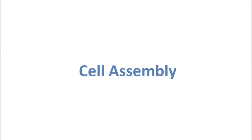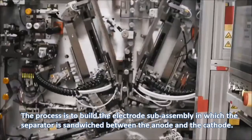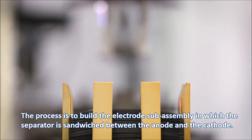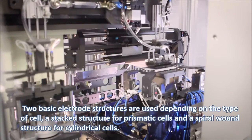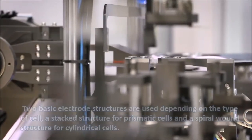Step 5, cell assembly. The process is to build the electrode subassembly, in which the separator is sandwiched between the anode and the cathode. 2 basic electrode structures are used, depending on the type of cell. A stacked structure for prismatic cells, and a spiral wound structure for cylindrical cells.